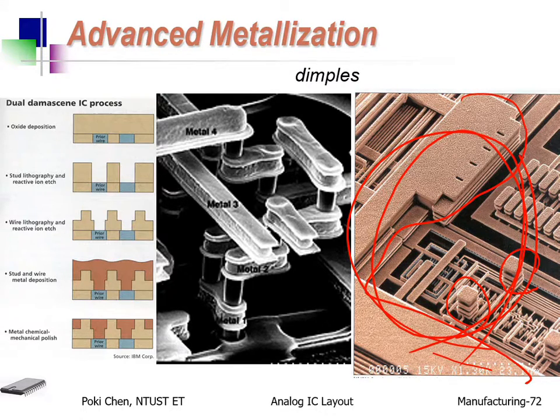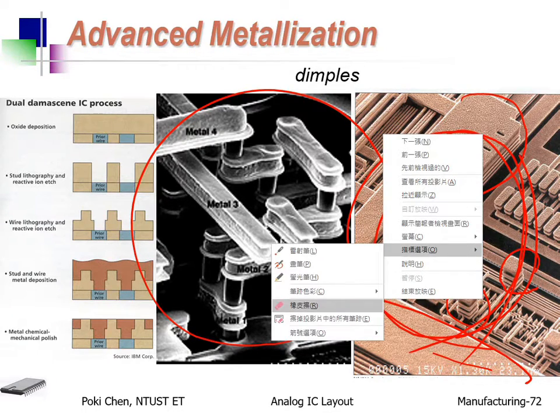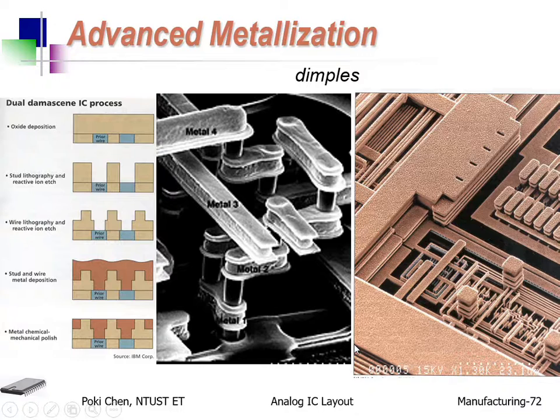Okay, allow me to show you some more detail. As I mentioned already, for metal layers, from the top one to the bottom one. Okay, how can you connect them? No single via can make it. So you can see from metal 4 via metal 3 via metal 2 via metal 1, and then contact to connect all the layers below metal 1. I don't care about any kind of layer below it, like gate, source, drain, body, blah blah blah, all of them.